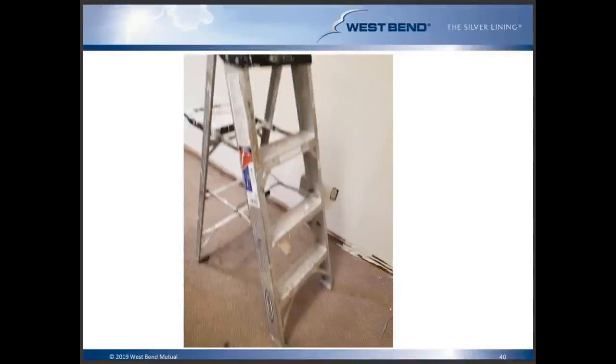So we talked about choosing the right ladder. In this case, this was an aluminum ladder, and if you look very closely at the outlet that's on that wall, you can see that it's missing a cover plate. So there could be exposed conductors with the cover missing, and a metal ladder in such close proximity could result in a serious electrical shock injury.